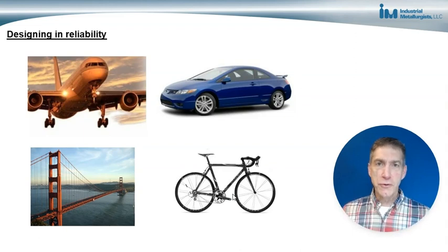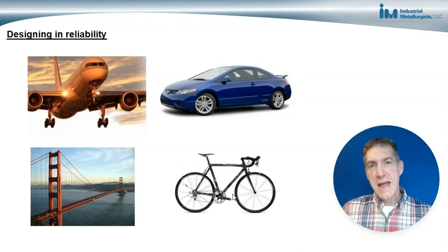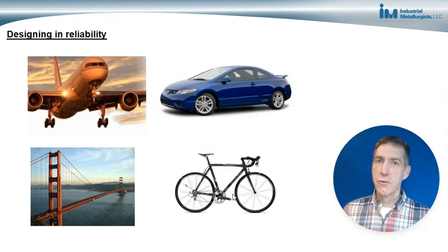And if we look at any product, we see it consists of a set of components that have been designed. These components have different materials in them, and they also have different shapes. And we have to figure out the stressors that the materials are exposed to. Stressors include corrosion conditions, wear conditions, fatigue conditions such as vibration or being exposed to alternating between a high and low stress. Also, exposure to ultraviolet radiation from the sun, biological agents such as components that go inside of our bodies. All of these stressors can cause materials to degrade.